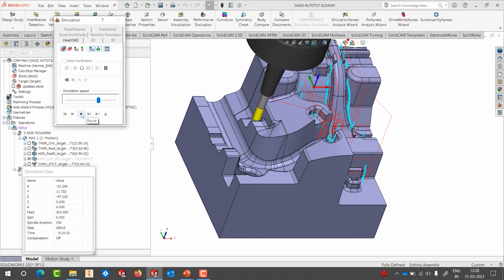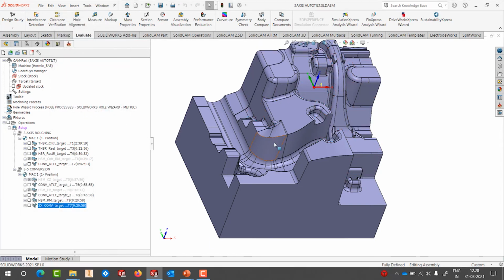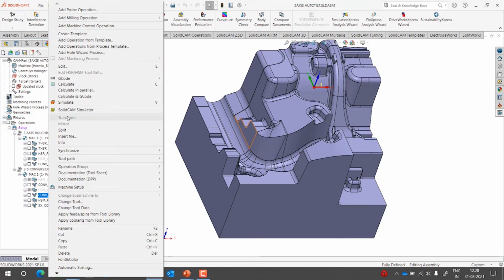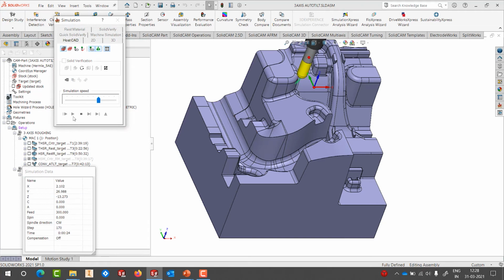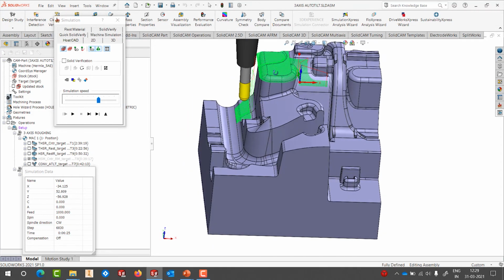So you can actually take any 3-axis toolpath, whether it is turbo or HSM, and you can just convert it using, for example, even if we simulate this one, this was the linear toolpath. You can take any of these toolpaths and just convert it using simultaneous 5-axis. It will take care not to touch. You can see that it keeps the distance between, so when it comes close, it tilts itself.